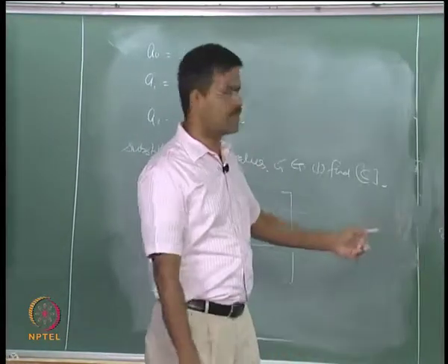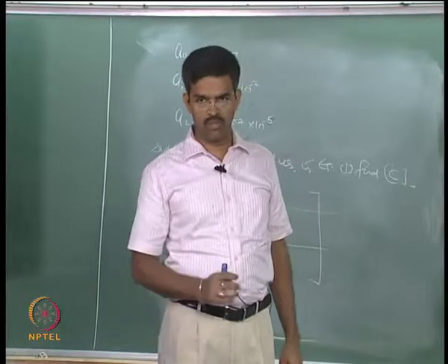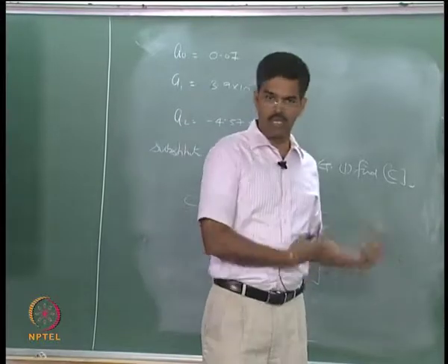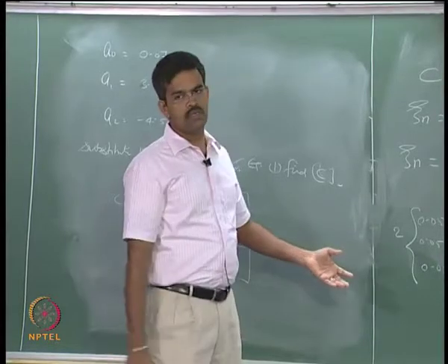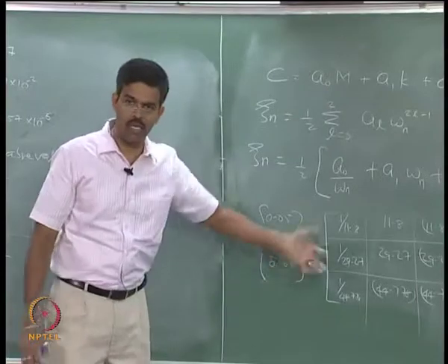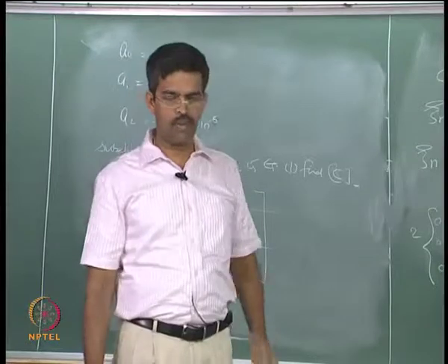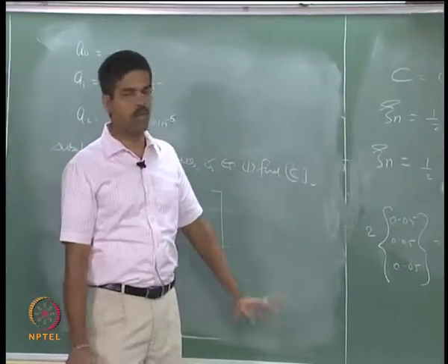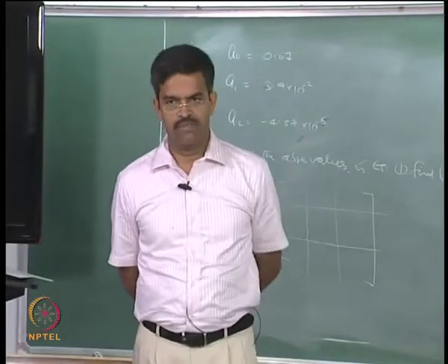Now, the problem with this particular series is that it skips different frequencies' contribution and forms an ill conditioned system. If you want to make it numerically stable, then I should include directly the superposition of modal responses or modal damping ratios on my C matrix. That is the third method we will see on Monday. We will pick up the same example, we will solve this problem in a slightly different manner and see how I get C. So, I get different methods to estimate the damping matrix, that is where we stop.